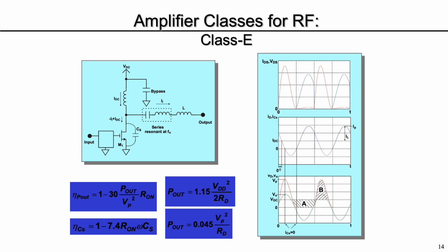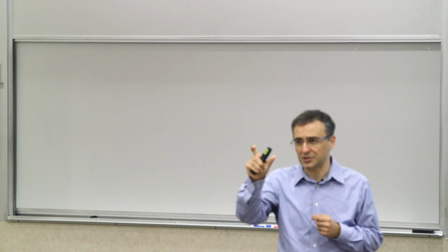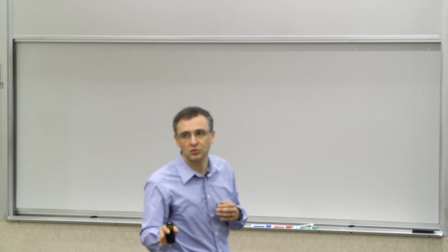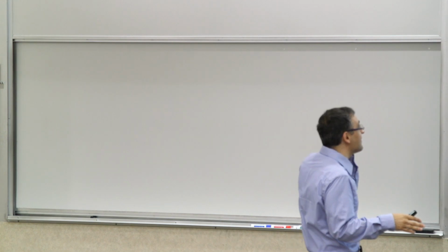So whatever you design for, you can allow for a certain amount of capacitor, and that capacitance becomes part of that network. In the network that you actually explicitly place there, you just account for the difference, whatever extra capacitance you need to get to that total capacitance. And this is a very useful property.